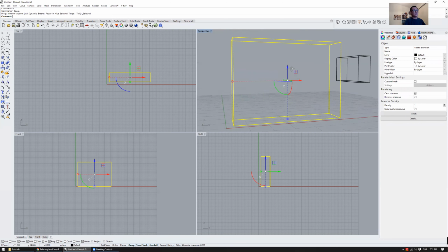So that's one direction. The other direction, going from lower right, is a crossing selection type. Anything that we cross or touch with the boundary of this rectangle will get selected. So you'll see, even though that only partially crosses this box, it selects it, okay? So it's just slightly different behavior. One needs to be completely enclosed, the other just needs to touch it at any point and it will select it. Those are the couple of selection modes that you'll probably come across.